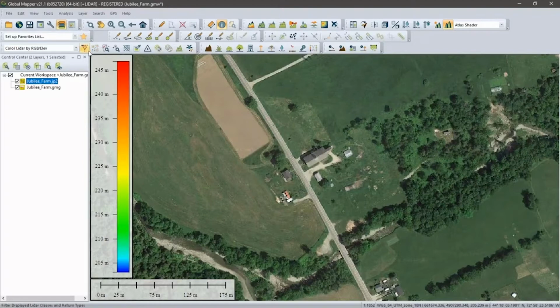So all the way along the bottom of my toolbar are tools that we can do things like do a comparison between point clouds, do a proximity search for points within a point cloud. We will be using some of these in our workflows, point cloud thinning, for instance. We can do a QC process on a point cloud to adjust its vertical accuracy. So this LiDAR module, as we call it, allows you to do a lot of really cool things with your point cloud. And again, we will see some of these a little bit later.